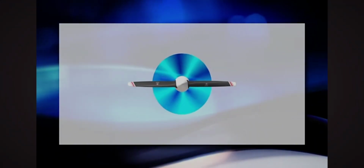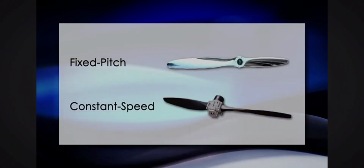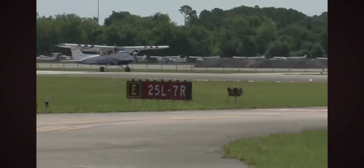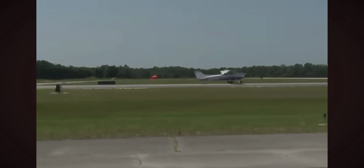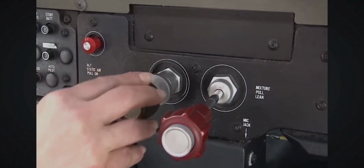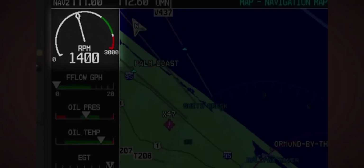Since the propeller rotates around its hub or center, the further the propeller extends out of that hub, the faster it spins. To create equal force throughout, manufacturers twist the blade. There are two major types of propellers: fixed-pitch propellers and constant-speed propellers. The Cessna 172 is equipped with a fixed-pitch propeller. This means that the pilot cannot manipulate the propeller blade. It is installed onto the airplane and will always remain exactly how it was installed. An airplane equipped with a fixed propeller only has the throttle to control the engine RPM and therefore propeller RPM.